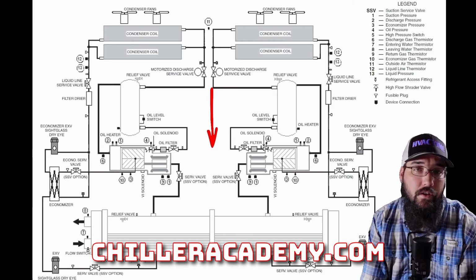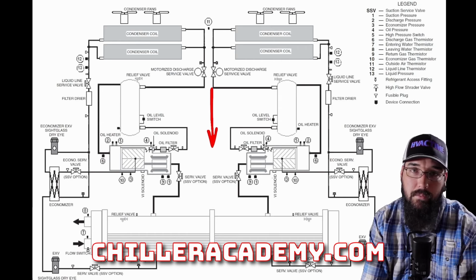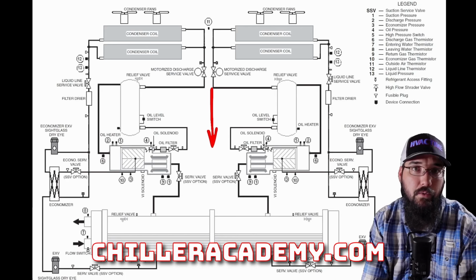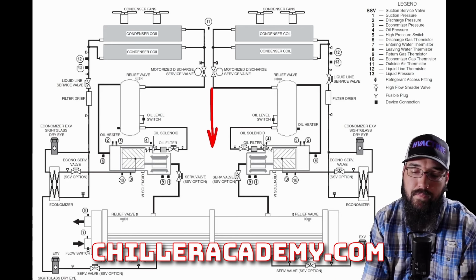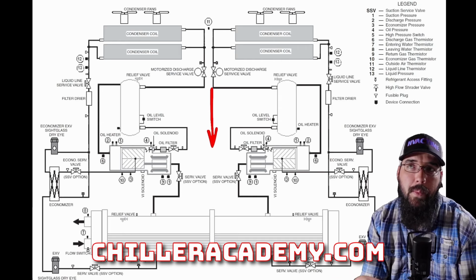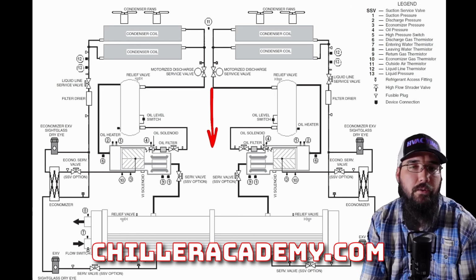Because a lot of these, the two most common evaporators, so you're not going to be dealing with brazed plates and stuff, and we'll get into this in more detail, but you're going to be DX or flooded, or falling film actually is the most common. So falling film and DX, and there are some floodeds out there, so those will be your three most common. If whatever circuit is not running, that part of the evaporator is just not activated. It's not actively participating in the cooling process.